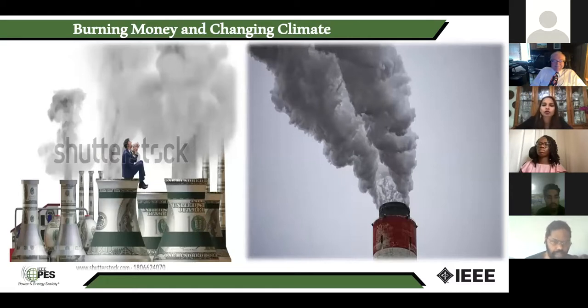So, burning money and climate change. Tripping. Why did I choose this topic? Just because when a unit is tripped, as I mentioned in the layout, the electrostatic precipitators are the ones that separate the dust particles, or the suspended particulate materials, from the system, and these are harmful. So the ESPs are designed to capture the emissions to a particular nominal level.